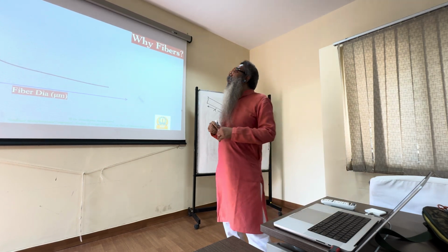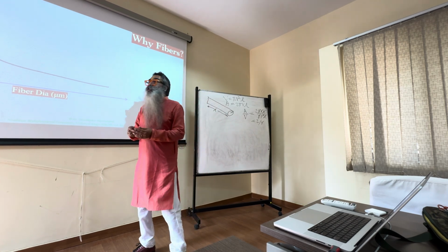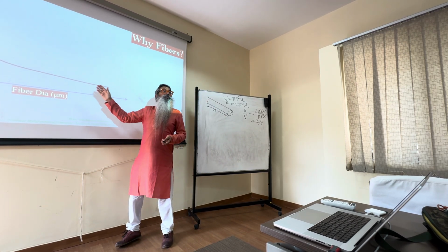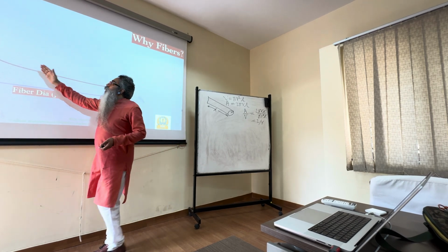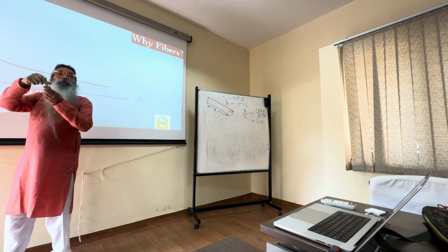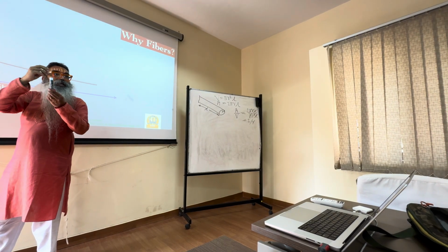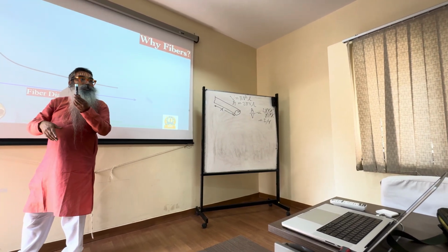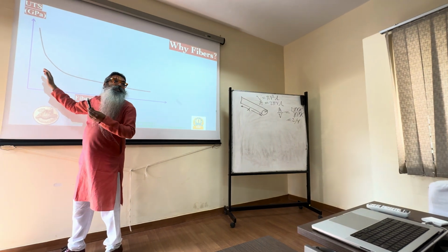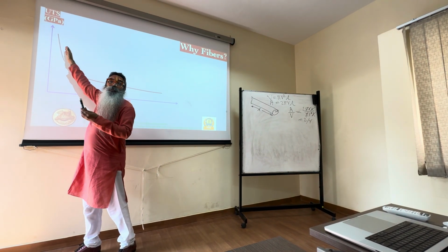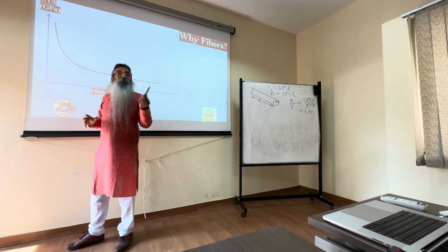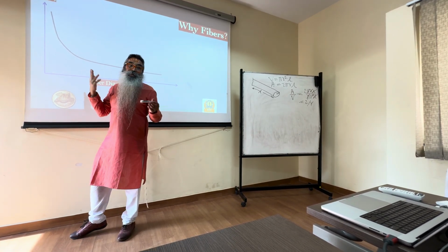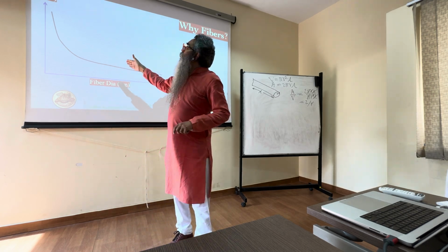That surface crack density is going to be much larger for larger fibers, and therefore their tendency to fail at a lower stress is more, whereas for very small diameters, the surface area is small, the number of defects are also small, and therefore the chances of reaching the idealization are much more. So that's why you go there. But we have stopped at a point, and you already answered that question, that it doesn't keep increasing forever.